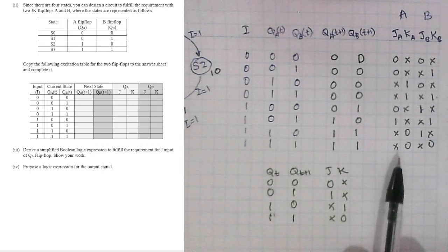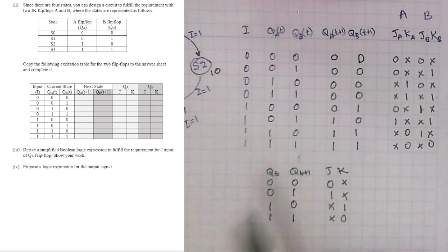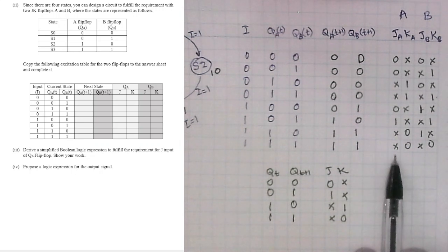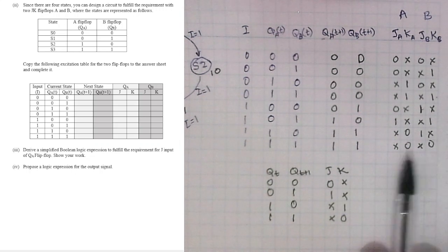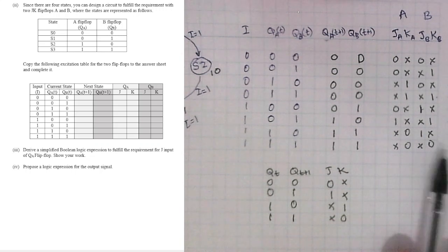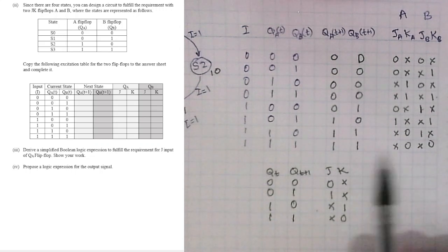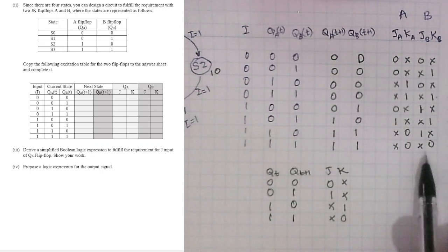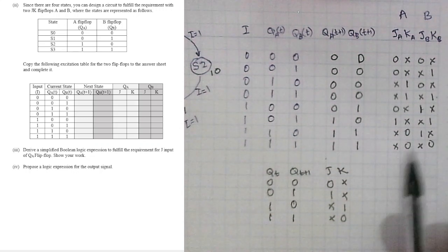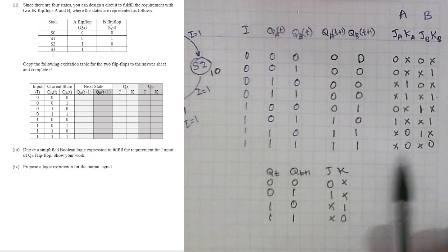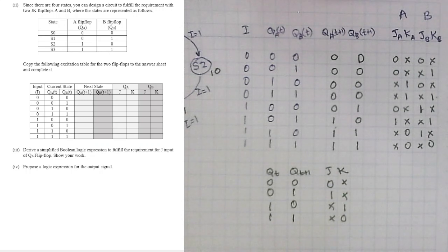So that's the entire idea. If we have these signals determined, then we can set them up as the inputs to our two JK flip-flops. We have a set of don't care conditions, and you can select each one of these columns and figure out a simplified circuit for that. Let's see how to do that.